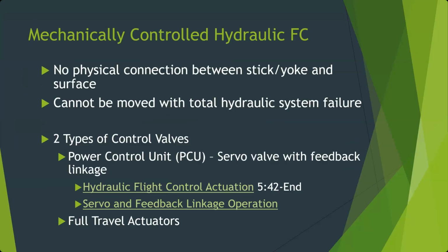So you may have systems 1 and 2 powering the left aileron, and systems 2 and 3 powering the right aileron, and maybe all 3 systems have actuators tied into the rudder.